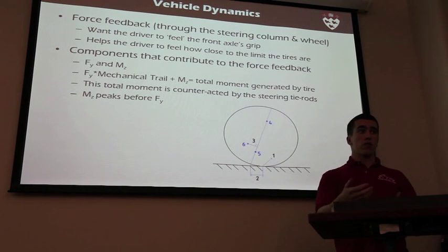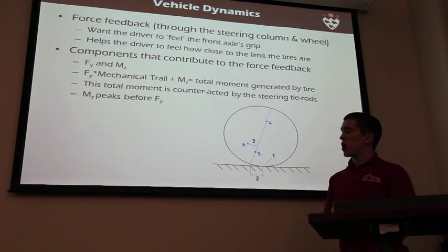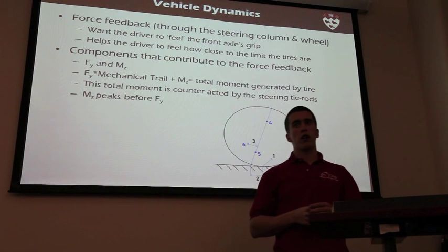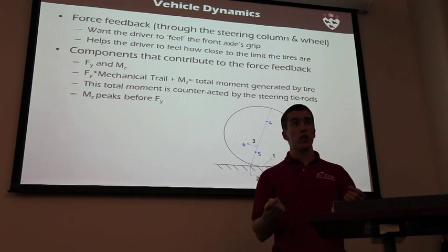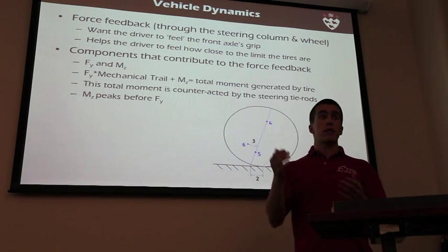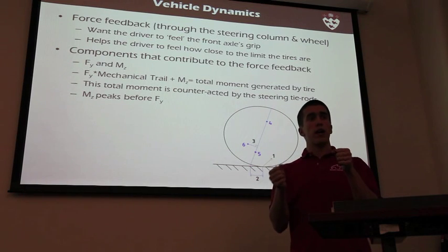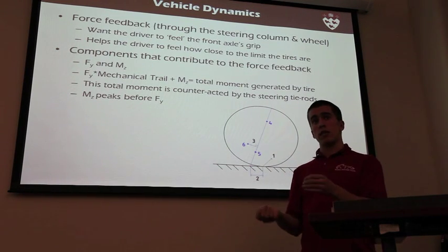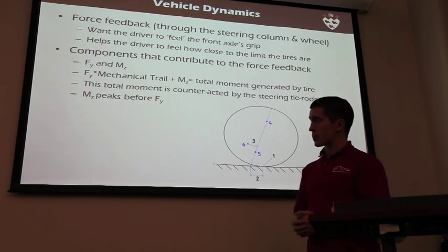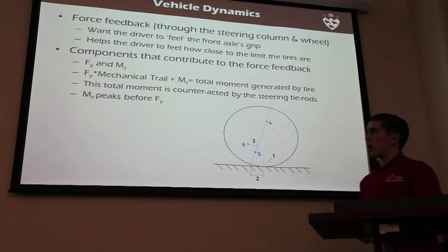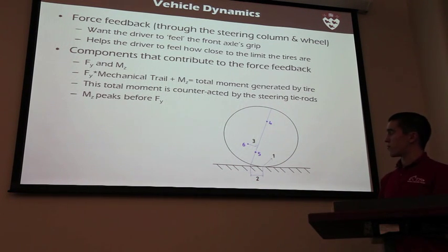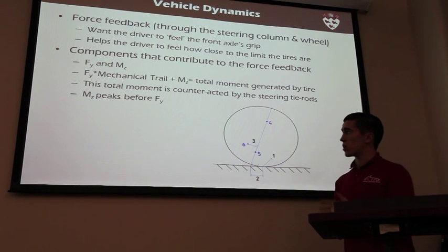So by adding the lateral force in the equation, you will basically give the driver a more accurate feel of what is the maximum lateral acceleration, because you will correlate basically the feeling of the steering wheel, which will have the highest feedback very close to the maximum lateral acceleration. So you play with these. Obviously there's a lot of different opinion on that subject.